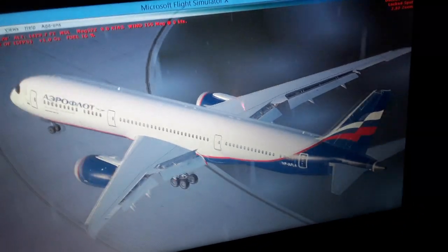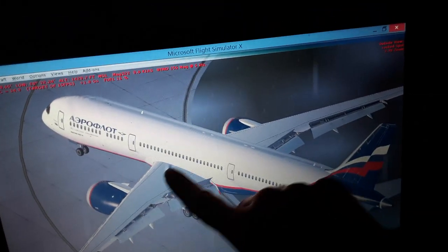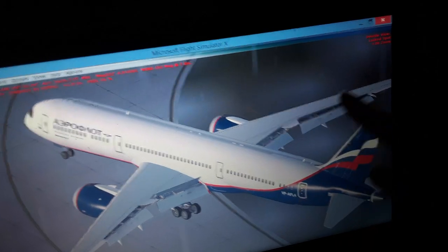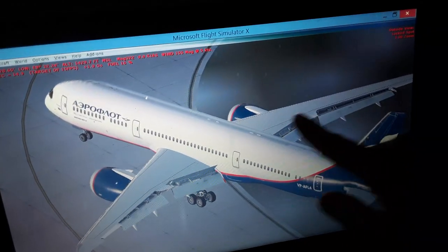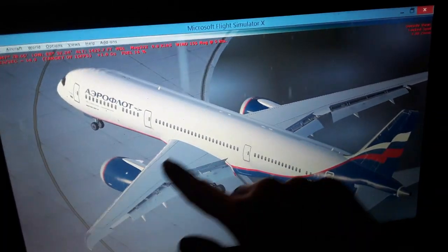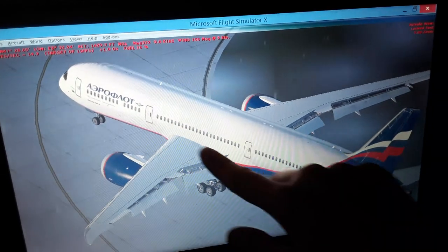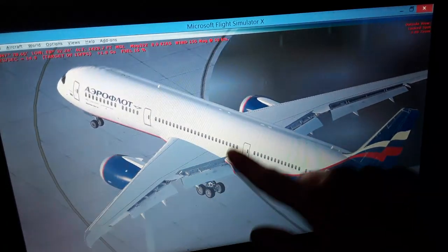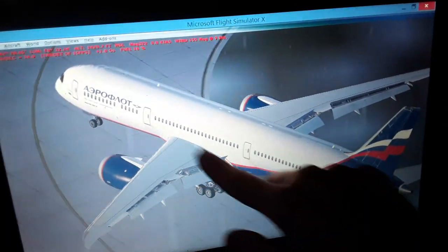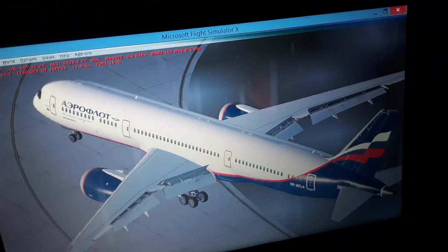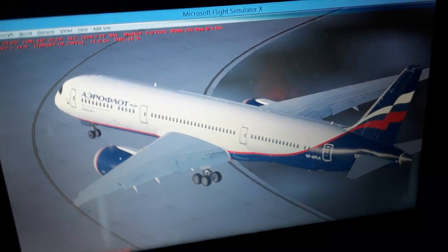You can see also here we have the aerodynamic chord position, the MAC, which is 23% for this aircraft, and these wings of the aerodynamic chord is where the maximum aerodynamic lift occurs in the flight, and also the position where the center of pressure is moving forward and aft over the wings, also where the airflow becomes detached from the top surface of the wings when we fly, and the aircraft wings stall.